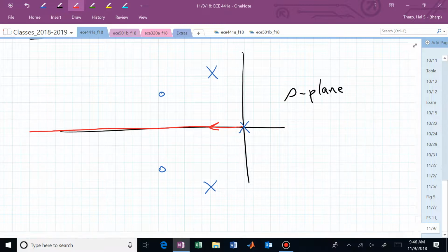We have 3 poles and 2 zeros. Our pole zero excess is 1. We divide that into 180. Our asymptotic action is just happening at minus infinity. So the other 2 branches terminate on finite zeros, and that's what our root locus would look like.